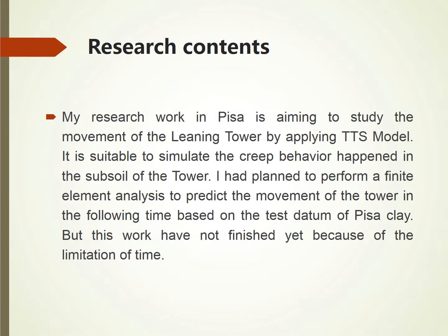My research work in Pisa now aims to study the movement of the leaning tower by applying the TTS model. It is suitable to simulate the creep behavior happening in the subsoil of the tower. I had planned to perform a finite element analysis to predict the movement of the tower in the following time based on the test data of Pisa clay, but this work hasn't finished yet because of the limitation of time. I just came here for 3 months, and I will keep working on this when I come back to China.